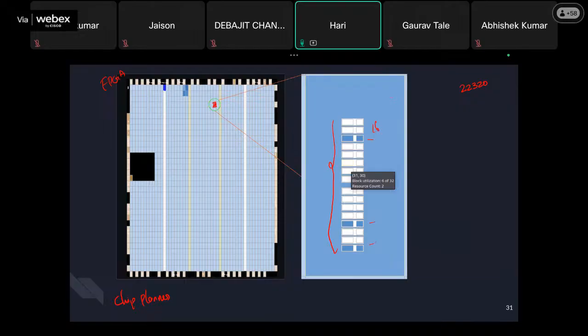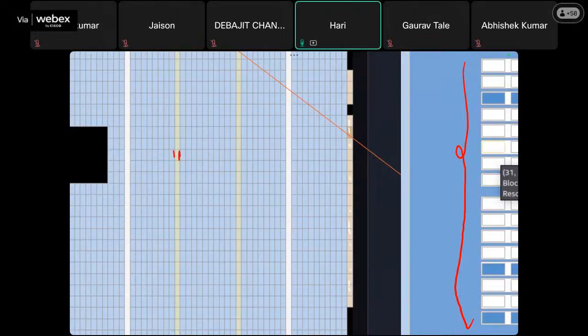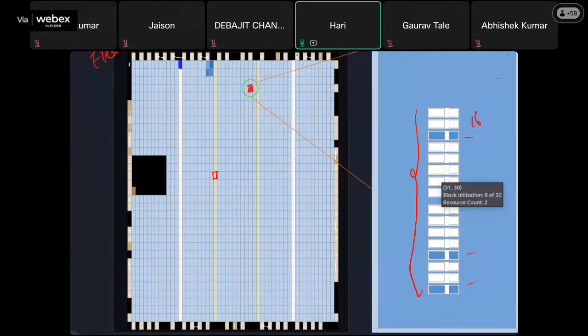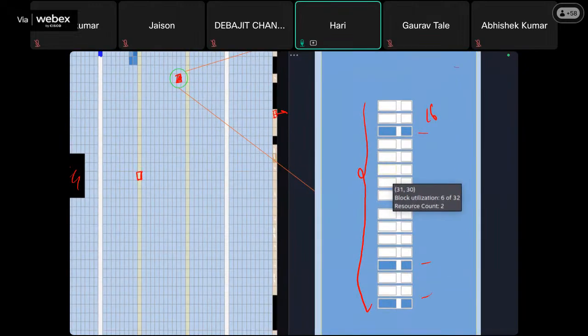Within that, I will show you how the LUTs, lookup tables, and the configurable logic block exactly look like. But apart from it, if you can see from this diagram, we have something else. We have this particular yellow line. These are embedded memory bits, and then the white fabric we have are programmable switches. Apart from it, we have some memory spaces. Apart from it, these brown colored things are IO pads, and IO pads are always with the IO buffers as well.